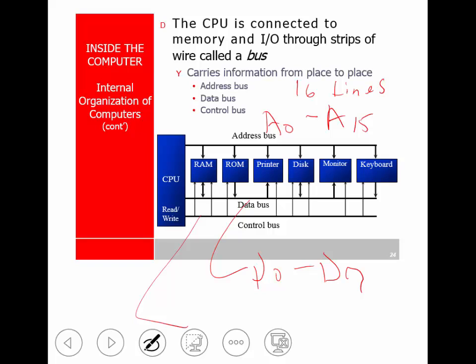And I was looking at the final for this class from last semester, and about a third of the questions involved in the final from that class, and probably that there, is how do we wire all this up? What do those wires mean? What memory locations are addressed? What I/O locations? So this is the hardware side, and that's a little bit more where this class is going to reside out there. So this is what we've got. But these are the 3 buses that we talk about: address bus, data bus, and the control bus. There's other buses that will pop up, but those are the 3 biggies right there.